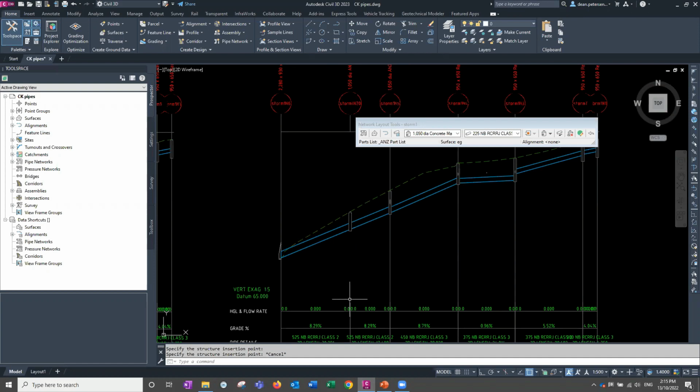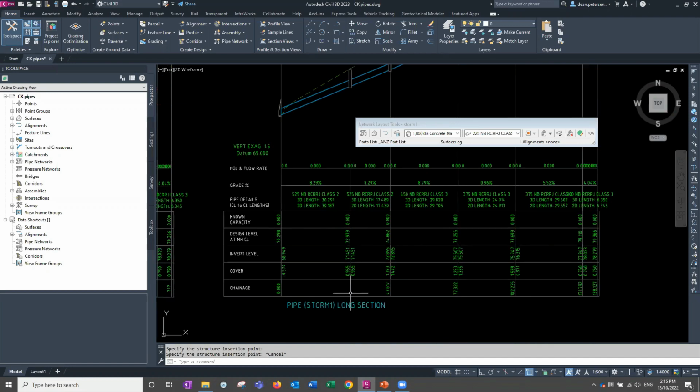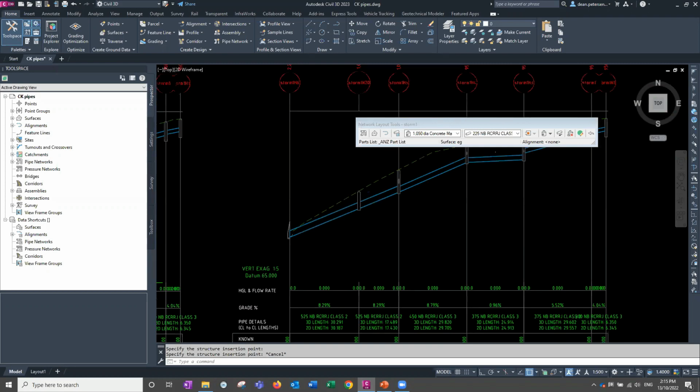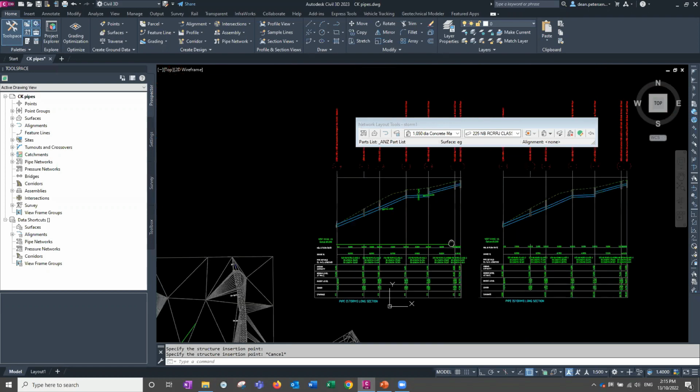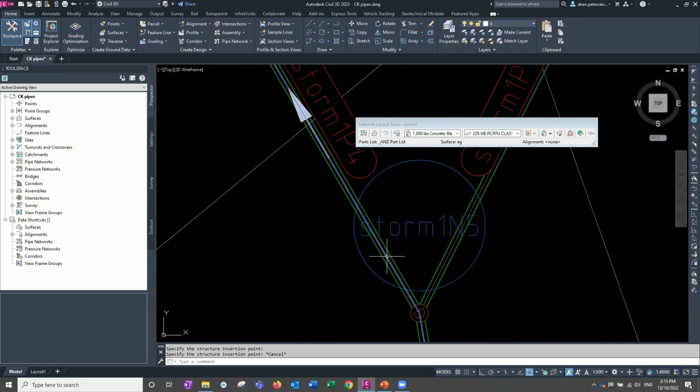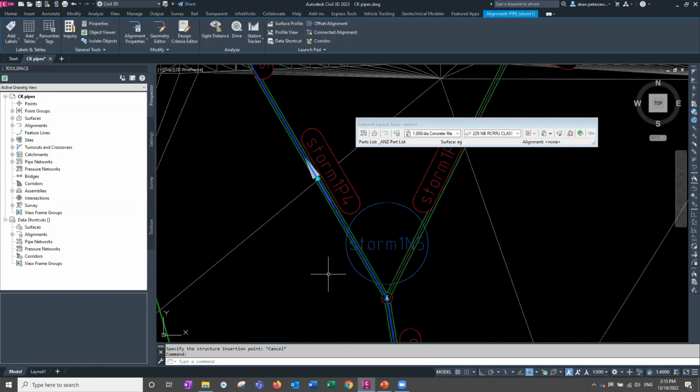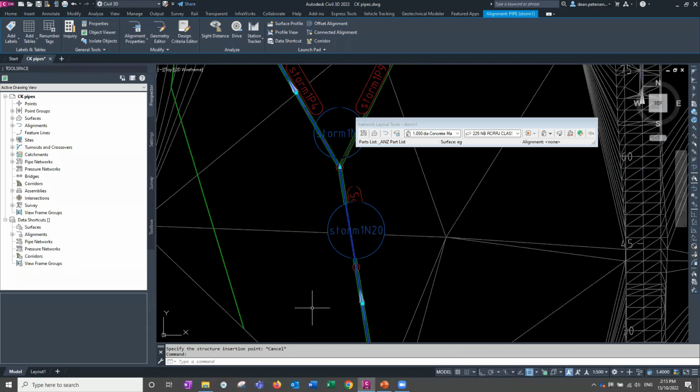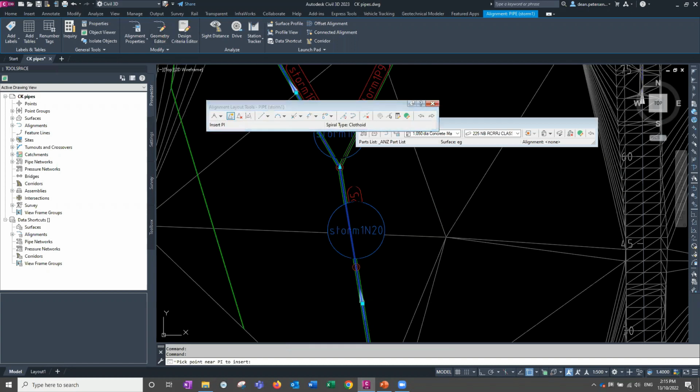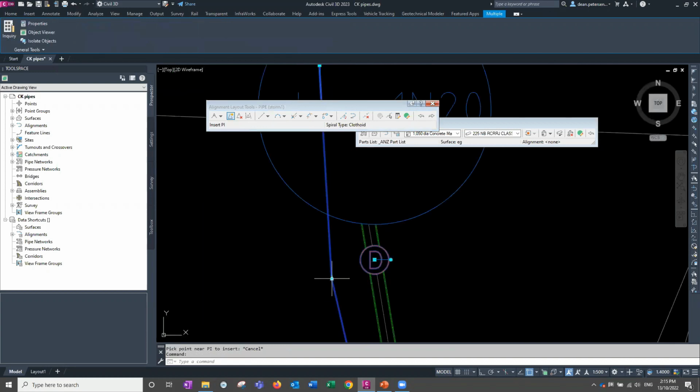However, what's not happening is this grey line is not showing, and it's not putting the chainage in either. You would normally have had to put in this grey line, so let's put that in. So what you have to do for that is go and find my alignment here, here it is, and put an IP point on that alignment that matches up to the location of that structure. So in the geometry editor, put an IP point, I'm going to pop it off to the side here, and then snap the two together.